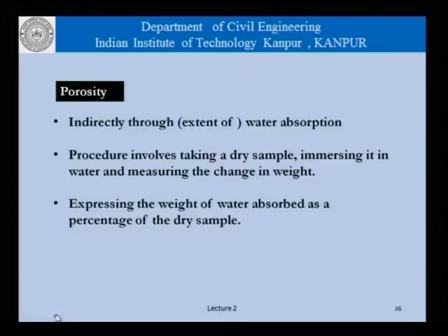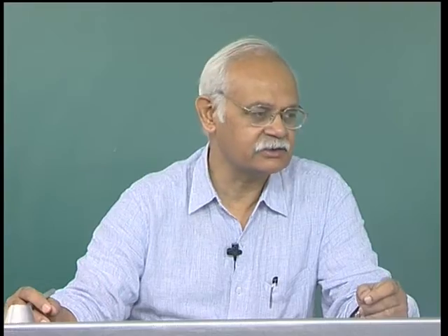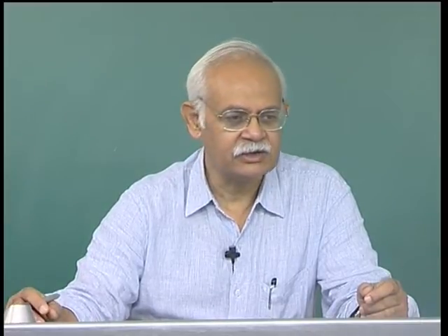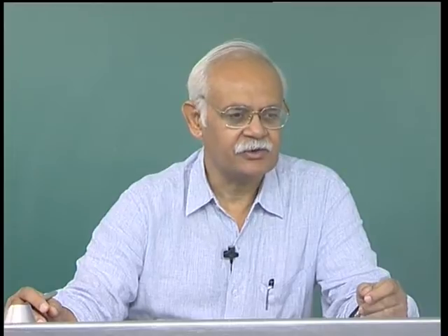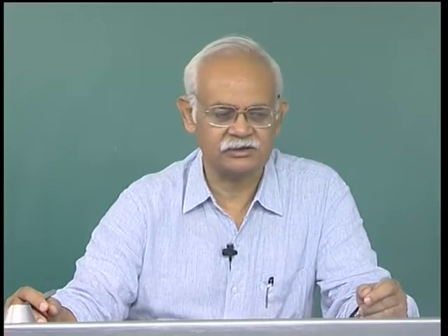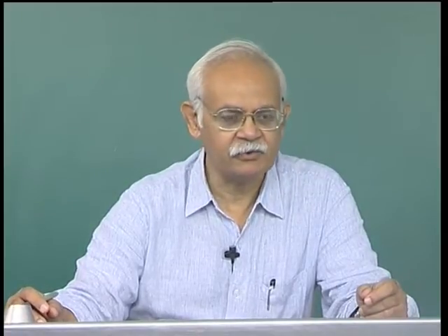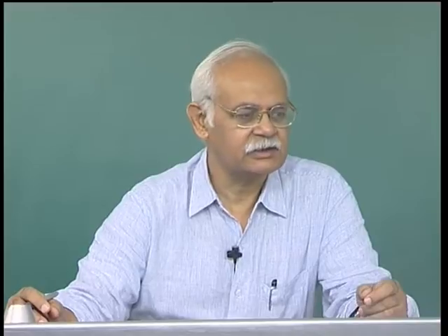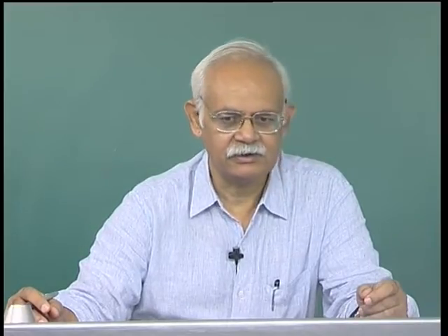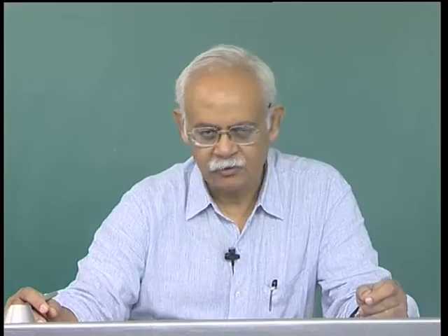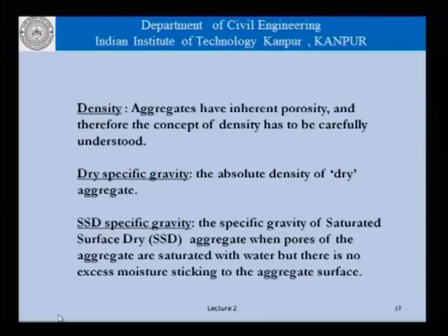Now, those are very fine, and techniques such as porosimetry and so on, which we will see later on in the course, are specialized techniques which for normal civil engineering construction and normal evaluation of aggregates are not required. Therefore, civil engineering practice has survived reasonably well, I should say, based on simple measurement of porosity as determined from water absorption alone. Now, other terms like density and specific gravity.